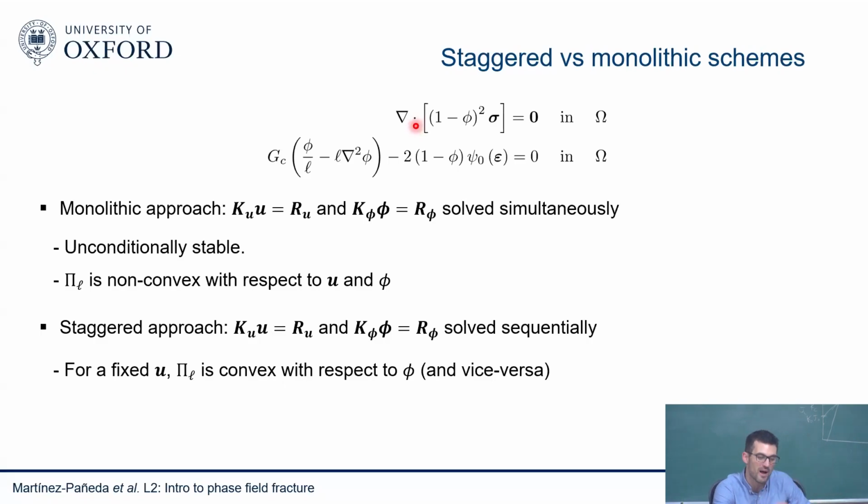So if you do single pass, you could lose the unconditional stability. Single pass can be a bit more robust, you'll get convergence more easily. So if you deal with a very complicated, nasty problem where you're not getting convergence, you can use the single pass. I don't think I've ever seen any problem where you don't get convergence with single pass, but anyway, we'll discuss that later. With single pass, you'll get convergence, but then you become kind of a forward Euler type of approach.